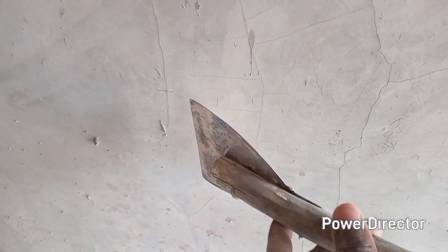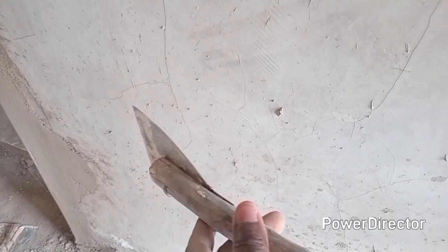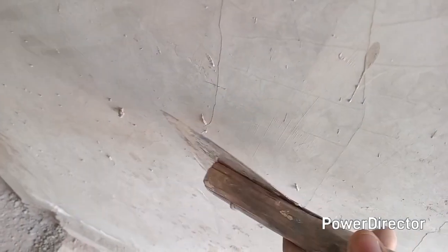So a wall like this one might look clean, but that is not the case. If you take a close look like this, you are going to see some unwanted cement splashes that splashed on this one when they were doing this job. And you cannot paint when the wall is having this. You are going to have a very, very bad outcome. So this one needs to be scraped like this, like that.